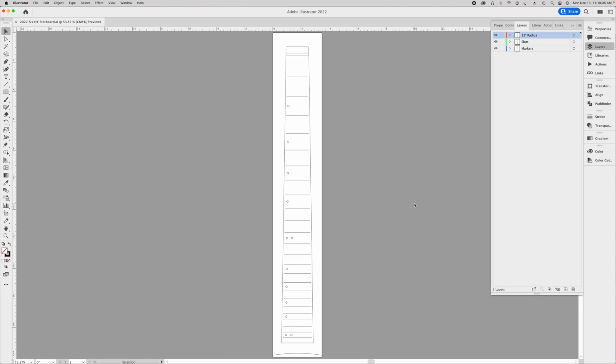Now, the question is, why all these different formats? Why do I need SVG and then a 3D format? Well, the SVG format works great for any sort of a two-dimensional carving operation. And that would include, for example, fret slots or fret marker dots. In the case of a guitar body, that would include pockets for the pickups, the controls, the neck, the perimeter shape of your guitar. Anything where you're cutting pretty much straight down into the wood and there's no three-dimensional contour involved.